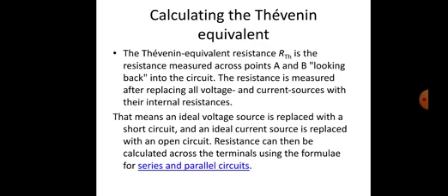Practical limitations. Many circuits are only linear over a certain range of values. Thus, the Thevenin equivalent is valid only within this linear range. The Thevenin equivalent has an equivalent I-V characteristic only from the point of view of the load.